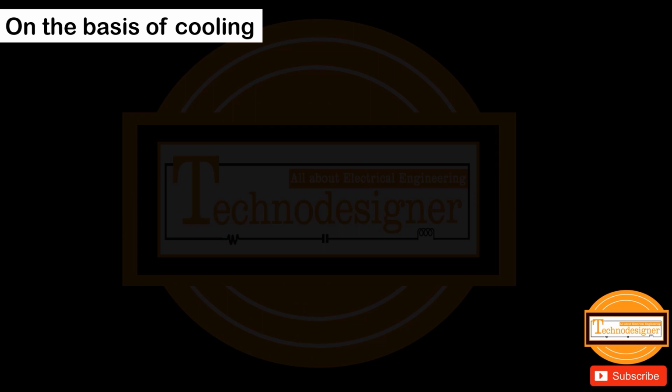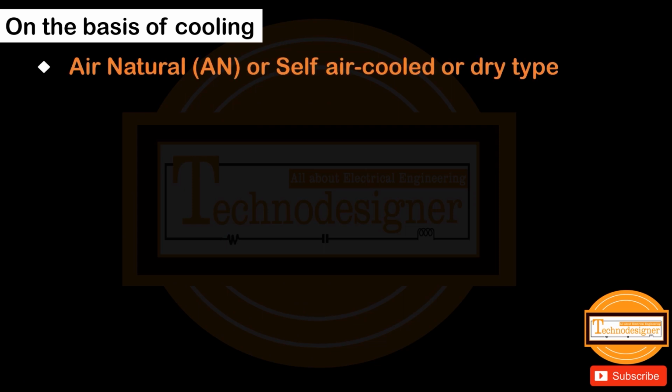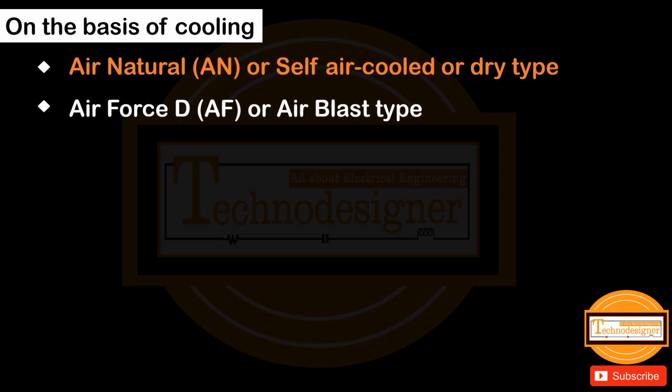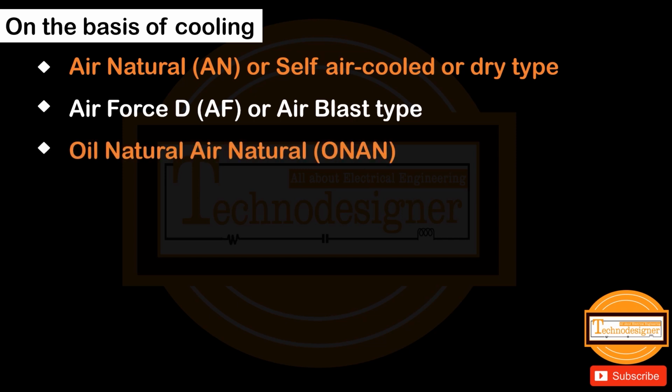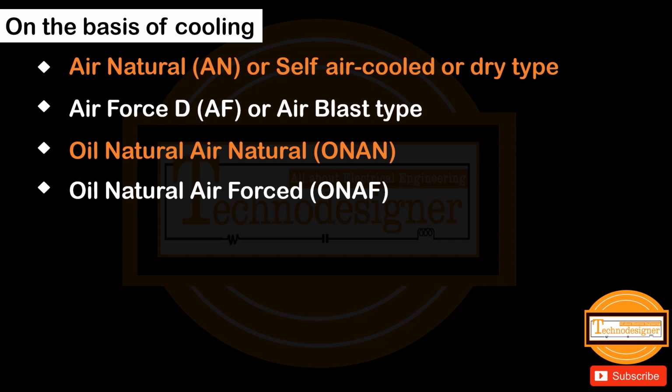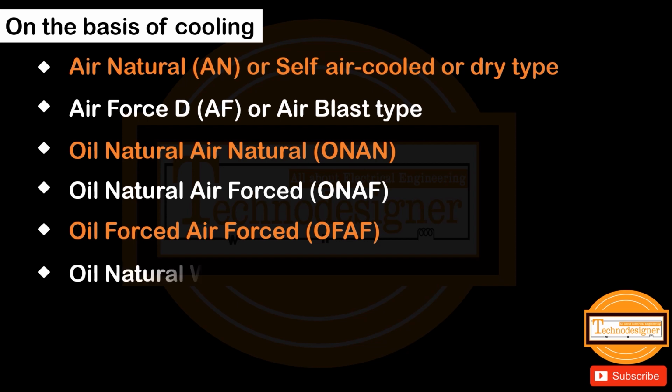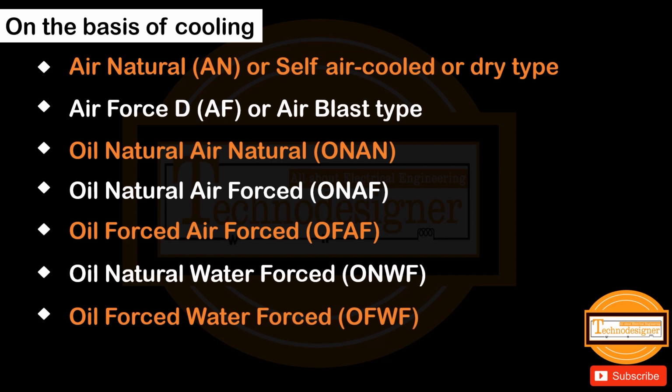On the basis of cooling: air natural or self-air cooled or dry type, air forced or air blast type, oil natural air natural, oil natural air forced, oil forced air forced, oil natural water forced, oil forced water forced.